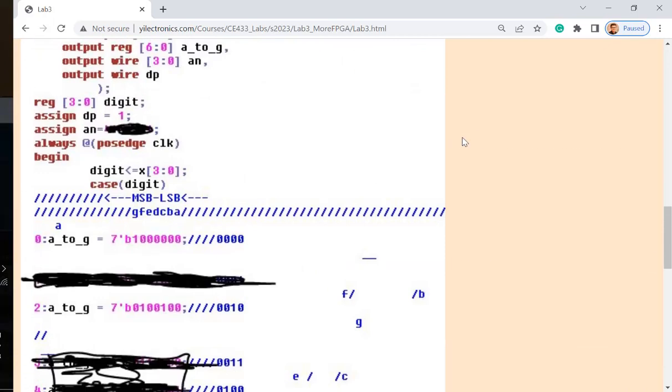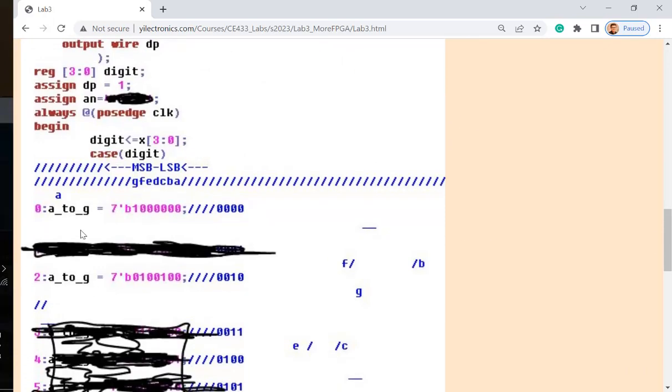So it's a case statement, like you learn in C++. I know it's a binary number, but Verilog can understand it. If your switch input is 0000, like a 4-bit binary number, it can understand it, not converting it, but understanding that you put a 0 here, which means it's just a 0, right?